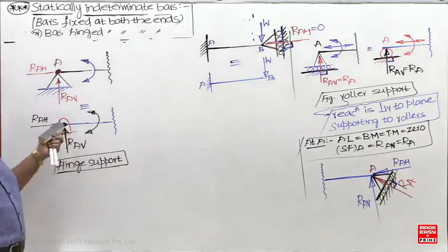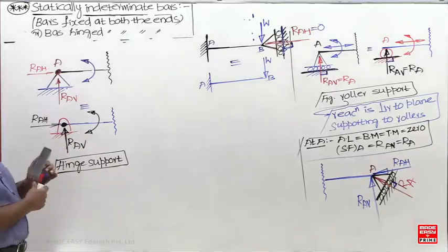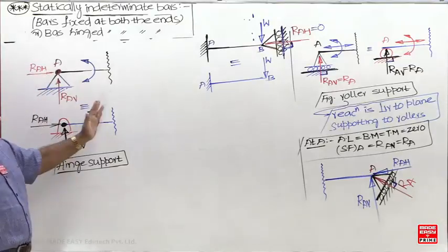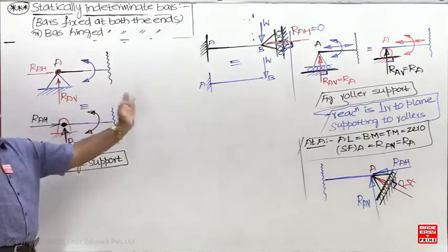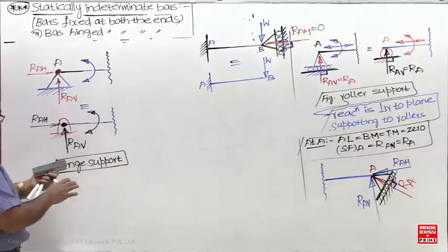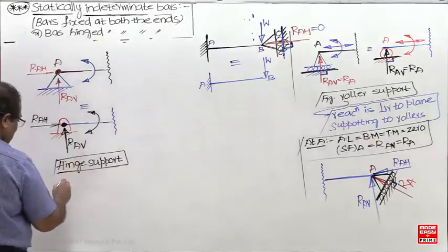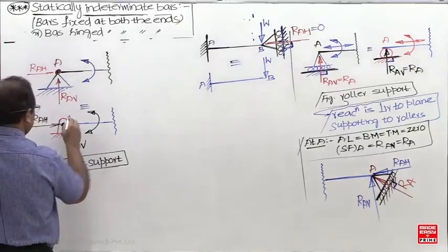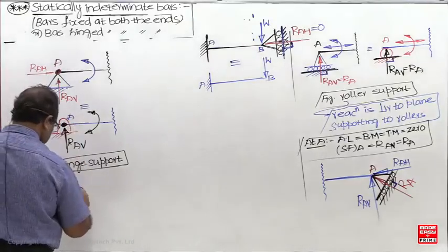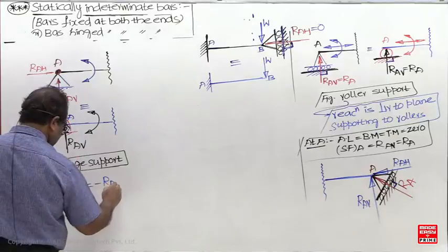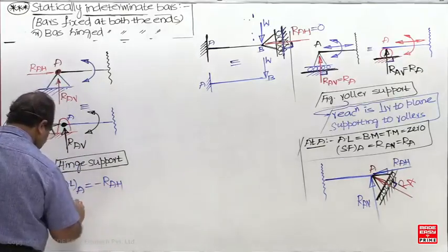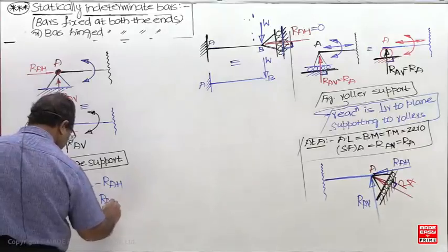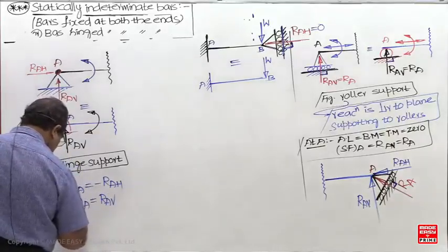Now this is once again, I have shown on the left side. So this hinge support is provided at the extreme left side. I have shown the left side portion, so the remaining portion will be on the right side. So here how many loads are possible? Axial load is going to be minus RAH. Shear force is RAV. And bending moment is 0.